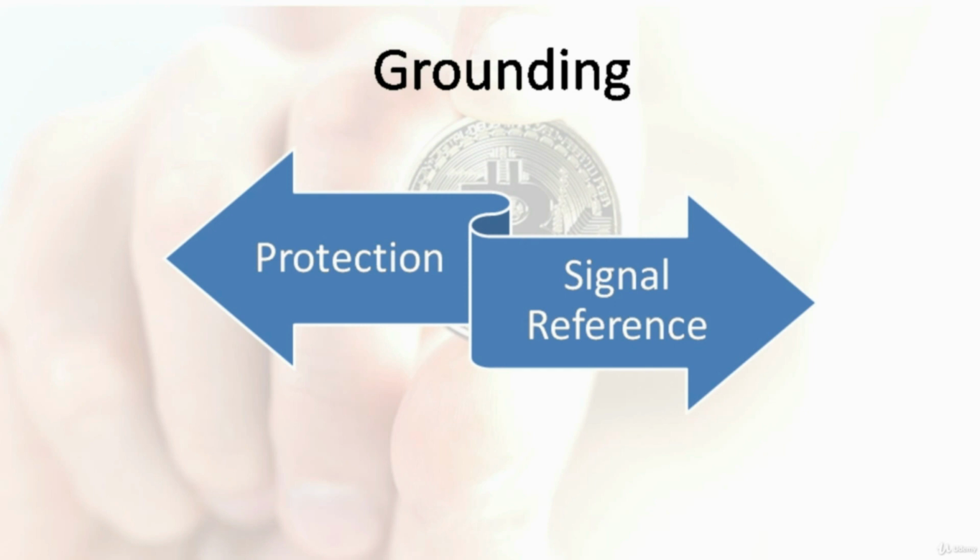Lastly, let us talk about grounding. For safety reasons, all exposed conducting surfaces must be attached to an earth point. This is to guarantee that any accidental completion of the circuit due to touching of the conducting surface would create a big enough fault current that a fuse or a circuit breaker would blow. If these exposed circuits or surfaces are not attached to an earth point, or in other words, left floating, the live voltage would be retained until someone or something makes contact with it, at which point they would form the conductive path to earth.